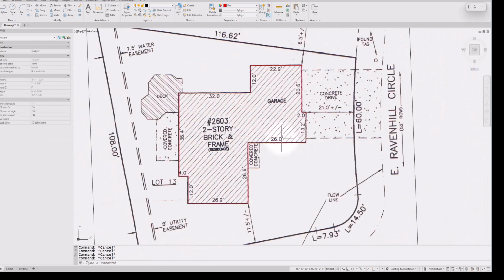So it's always great when the lines actually touch each other. Now we can do an offset of 6 inches. Note that I didn't have to put anything after the 6. It automatically is going to default to 6 inches. And so now we have a house footprint in record time.